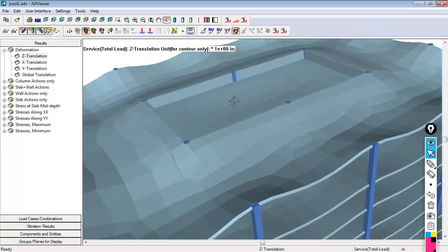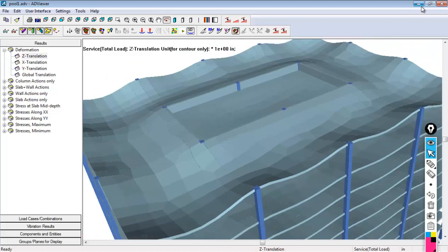Now if you have a similar condition where the story height is short, you could model, again, walls in lieu of the beams with some of the restrictions we've discussed earlier in the video. But it would require you, instead of running it in single level, even though the model itself may only be one level, it requires you to run it in multi-story mode.